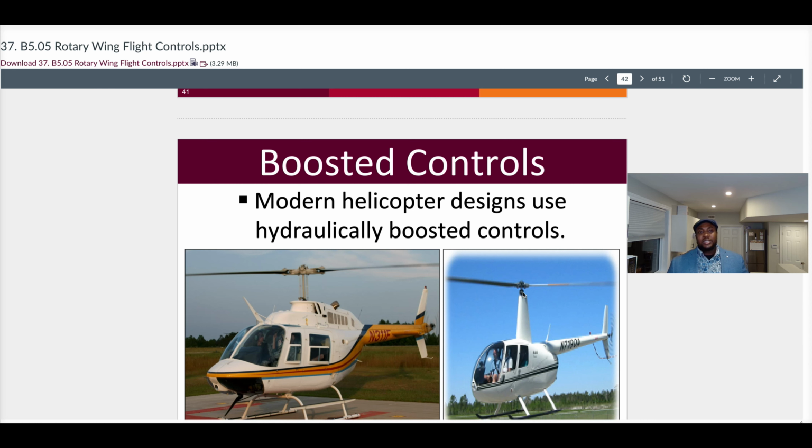But the next one is actually to dampen the feedback vibrations that come from the rotors. So the main rotor and the tail rotor produce feedback vibration that if it's not properly dampened can be felt like a buzzing from the tail rotor on the tail rotor pedals, or some kind of a pulsation from the main rotor.